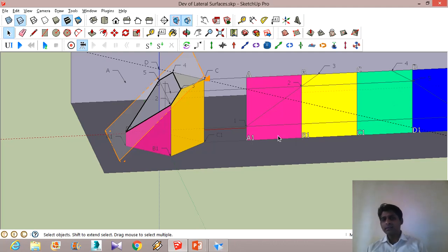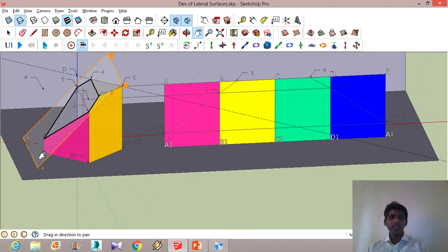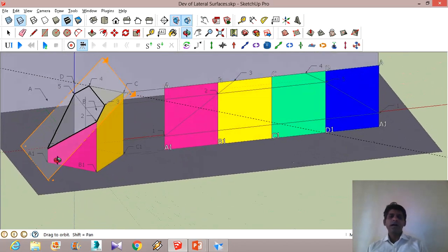So this length, or you can say the perimeter of the square, the perimeter of the square of 30 mm sides is 30 plus 30 plus 30 on the back side and 30 on this side. So it is 120. So the length from A1 to A1 has to be 120 millimeters, and A1 to B1 has to be 30 because it has to represent this particular edge here.